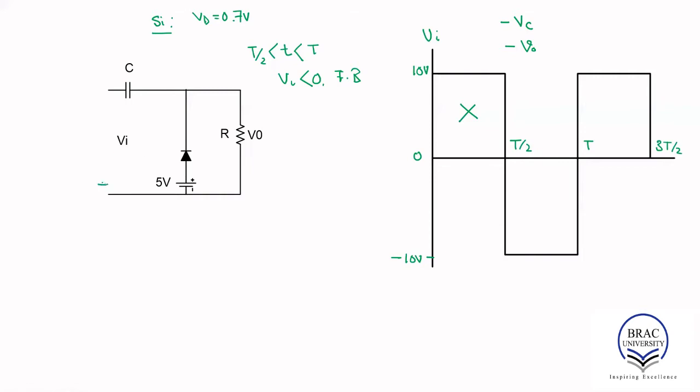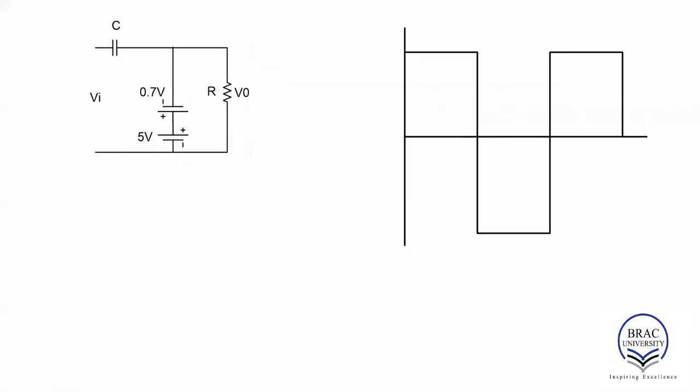So let's say this is our polarity. And for that, the diode appears to be forward biased. So as the diode is forward biased, the current is flowing through the diode. The real current always flows from the positive terminal to the negative terminal through the external circuit. So as the current is flowing through the diode, it is going to flow through the capacitor.